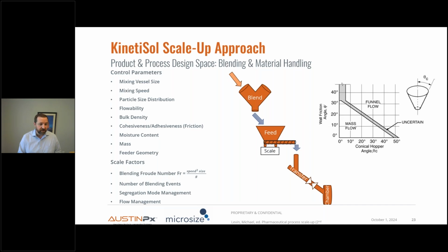We need to manage vessel sizes, we need to mix to create blends, we need to understand the particle size distribution of our supply chain, and make sure the material has the flowability and density parameters that are necessary for it to flow into the system. And if the formulation requires some physical adjustment in order to ensure this, then we make those changes.